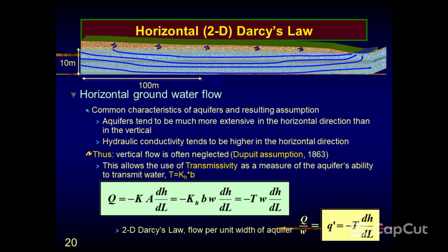Sources, as the name implies, they add, isn't it? They are adding probably flow, they are bringing something to our domain of interest. Sinks, they are taking out. When you have a test well, a pumping test, you are taking water out. That is a sink, isn't it? When you have a recharge well, you are adding to the domain, isn't it? That is a source. Are you following? These are very important terms when it comes to modeling, any modeling.